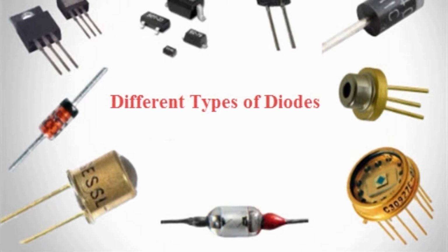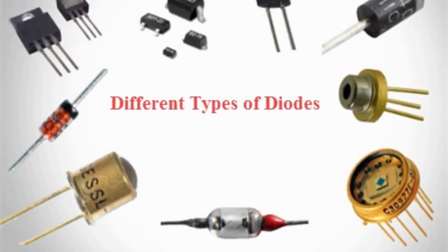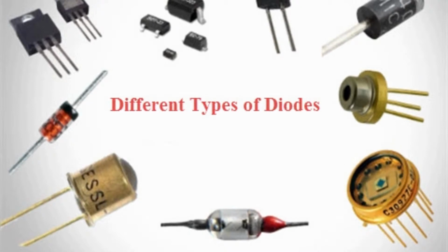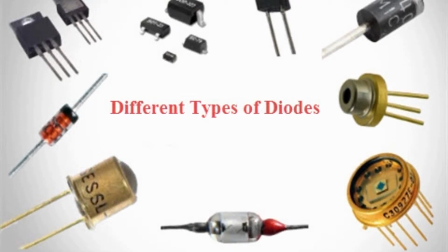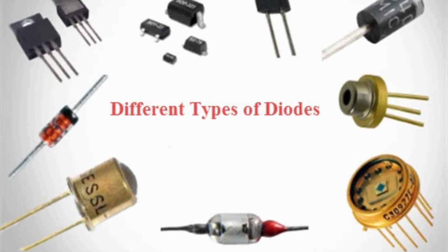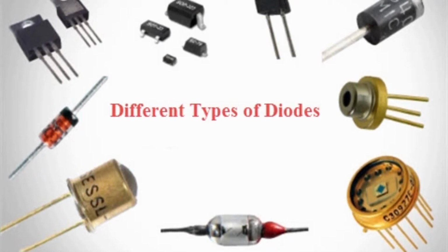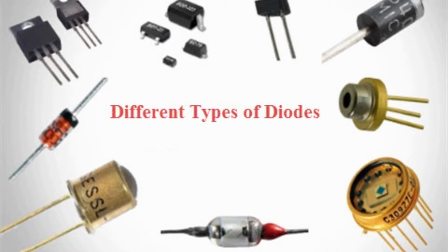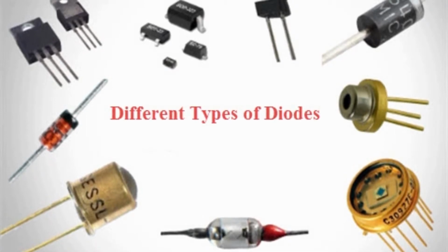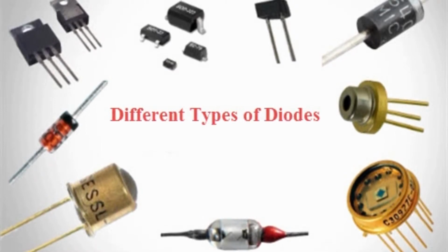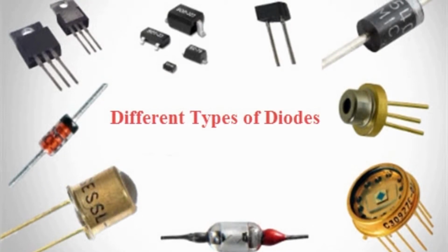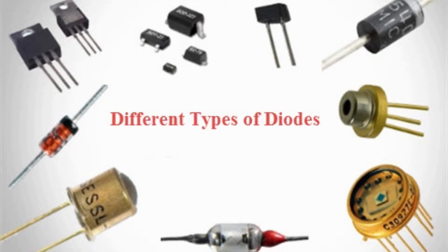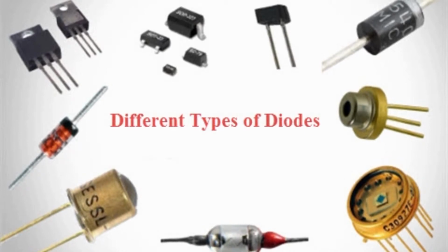During the on state, the practical diode offers a resistance called the forward resistance. The diode requires a forward bias voltage to switch to the on condition, which is called the cut-in voltage. The diode starts conducting in reverse biased mode when the reverse bias voltage exceeds its limit, which is called the breakdown voltage. The diode remains in the off state when no voltage is applied across it.